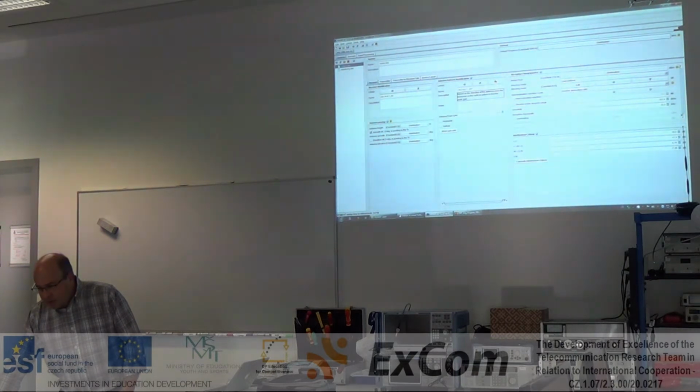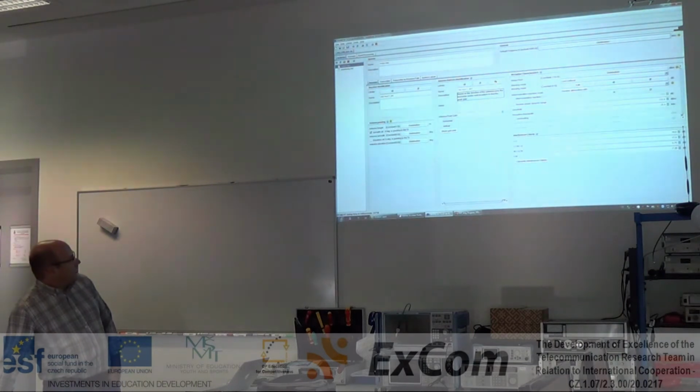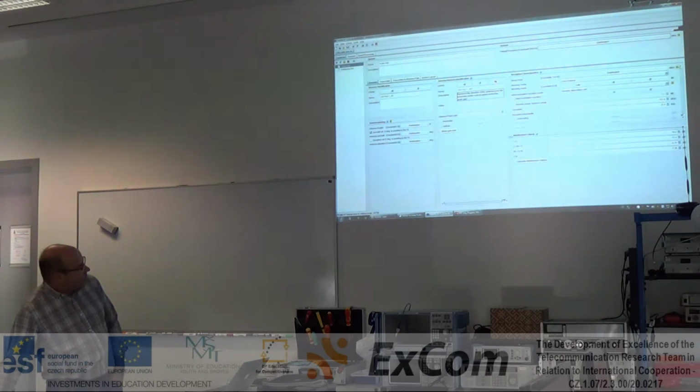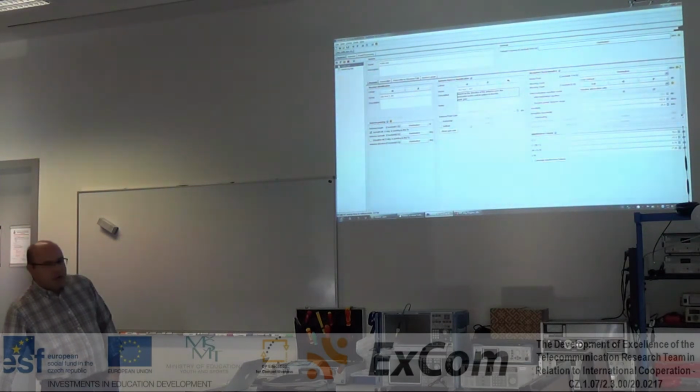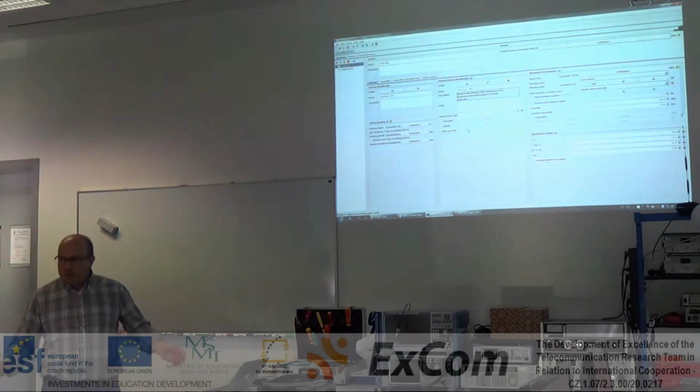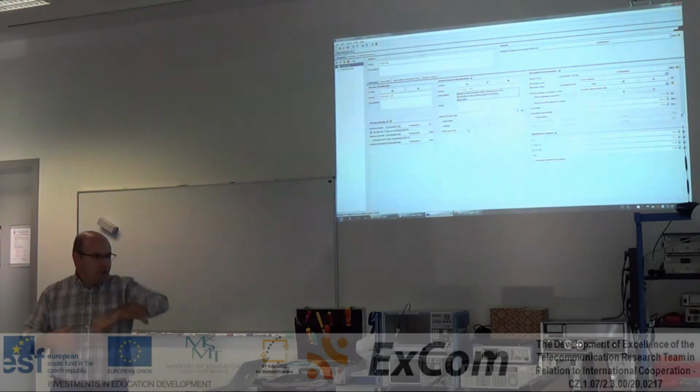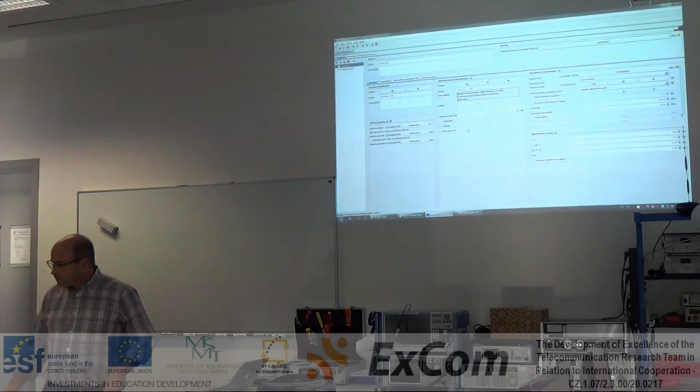Okay, here on the receiver you have the receiver ID. Here you have the height of the antennas, the elevation. You can define the azimuth and elevation. On this window, I will open it a little bit to see everything. You can define the antenna peak gain, and if you want, you can define the horizontal and vertical patterns. For the moment, they are not checked, which means that the antenna is omnidirectional, horizontally and vertically.